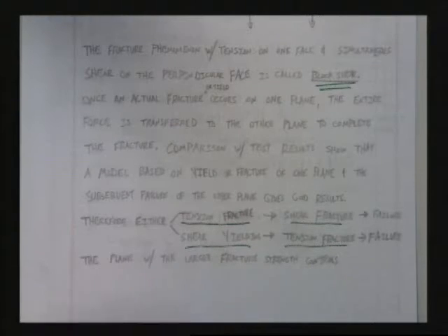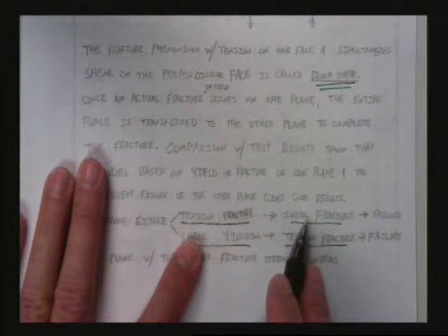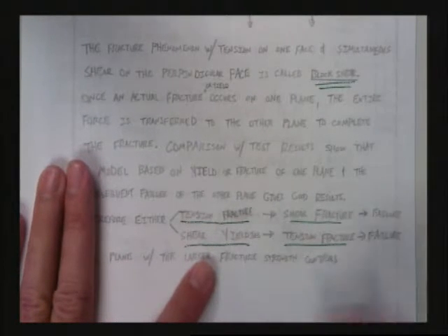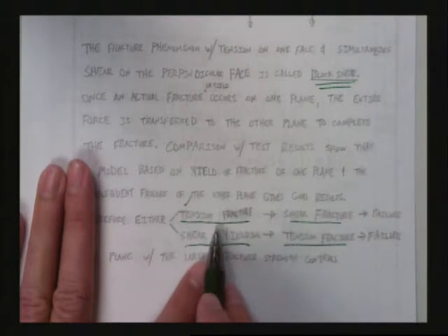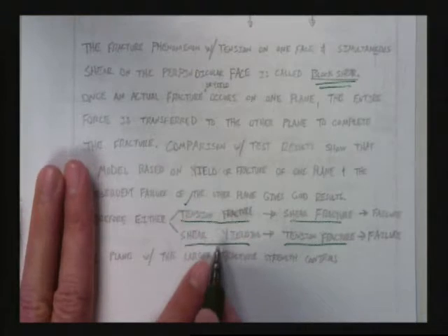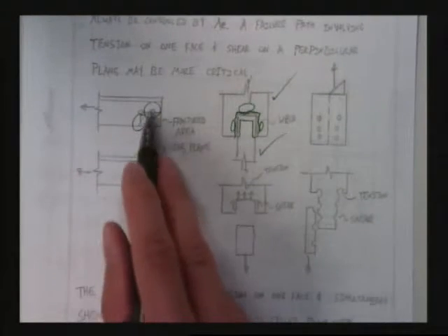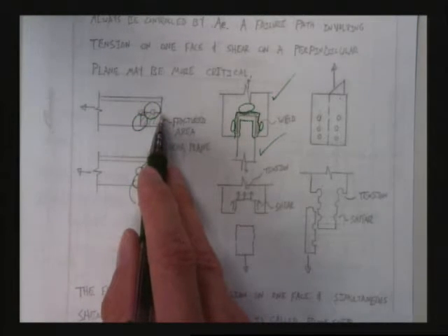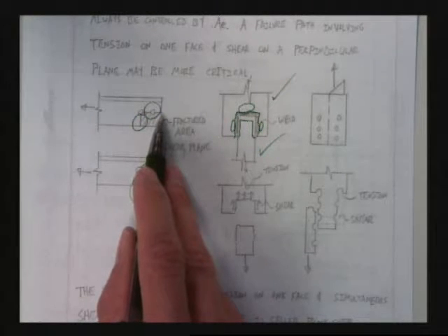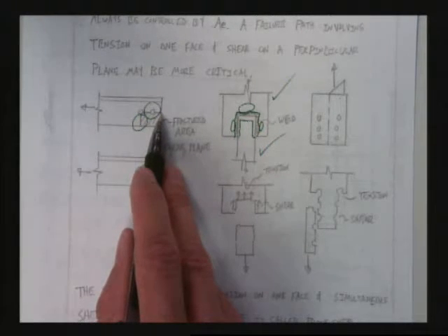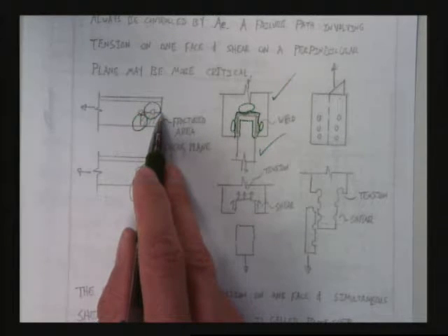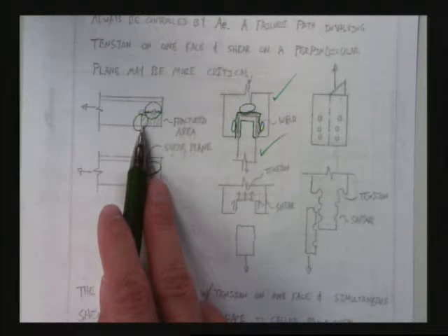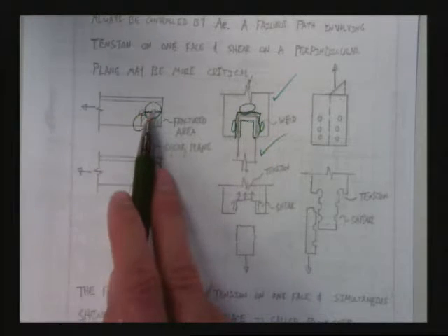Now, what people love to say is, okay, I get this one, fracture and fracture, that makes sense. But how does this yield and fracture work out? Well, remember, this is what we call case 1, and case 1 typically controls more than case 2 does. However, there are phenomena where, if that shear plane is long enough, all it takes is the yielding. Because when things yield, what happens to stiffness? It's nothing, right? So if there's no more stiffness up here, then all the load has to be taken by this, right?